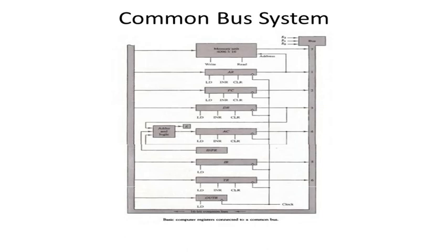Write means the data is transferred from the bus to the memory, and read means the data is transferred from memory to the bus or to some other unit connected with the memory. And suppose this multiplexer input is 1, then automatically the address register will be selected.